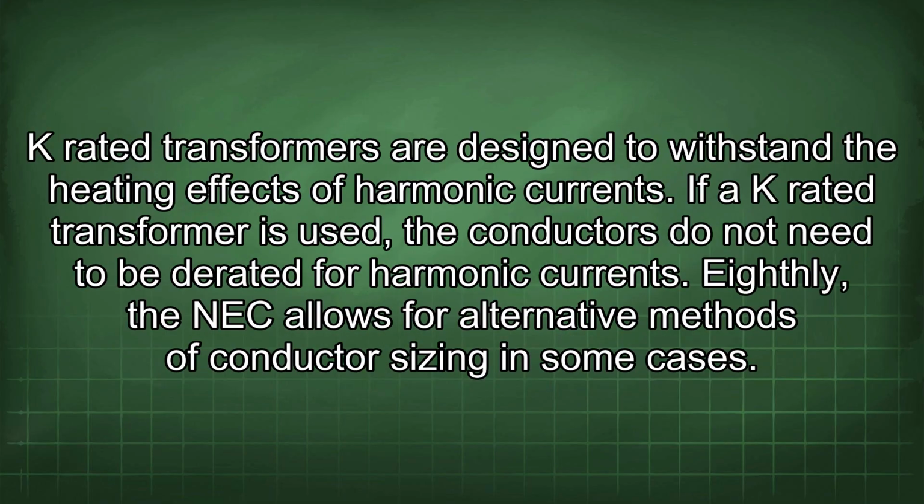K-rated transformers are designed to withstand the heating effects of harmonic currents. If a K-rated transformer is used, the conductors do not need to be derated for harmonic currents.